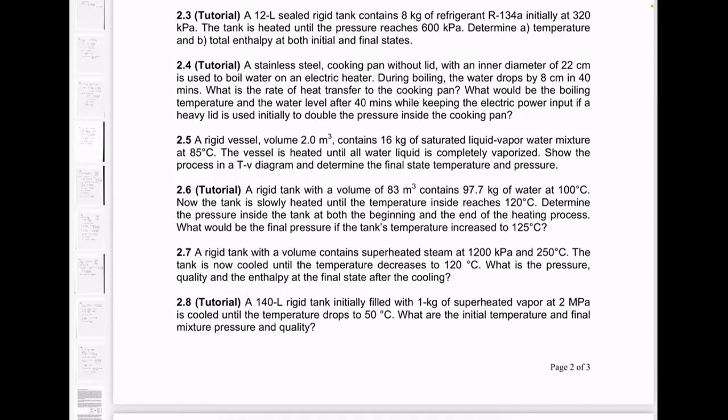So we're boiling something, we're losing some amount of water per unit time because it's being converted into steam. Now, when something's being converted into steam, what's happening? We're adding enough energy to take it all the way enthalpy-wise from HF to HG. Okay? And again, enthalpy is always in terms of kilojoules per kilogram. So if we can identify the state that this is in, then we can find HFG.